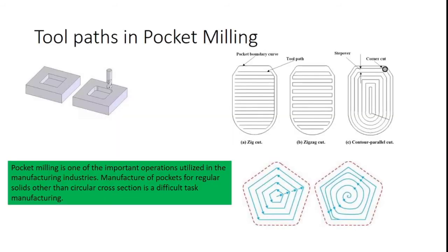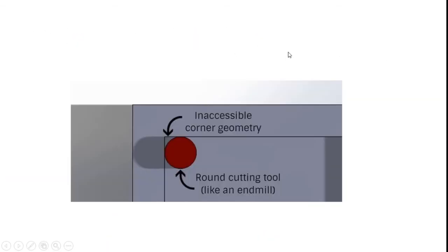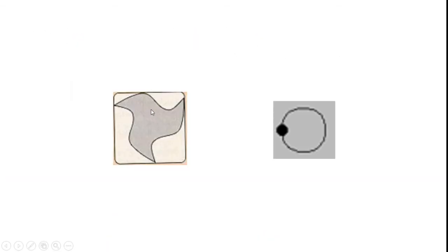Let's see. Here I convert that Reuleaux triangle into an end mill cutter shape. I introduce the relief angle, drag angle, and clearance angle with the Reuleaux triangle, and then I can make a Reuleaux tool profile. After that, I also create the centroidal path.